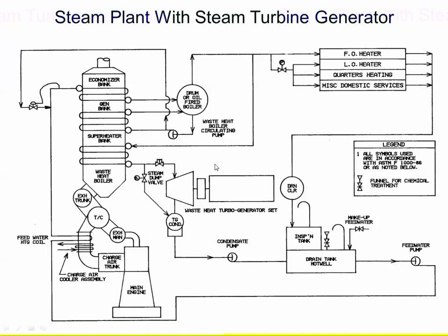And then here, my saturated steam is going to go through a superheater and into a steam turbine. The other thing I'm going to mention on this one is that it also has the steam dump here. But on this type of system, at sea, you control boiler drum pressure with load on the generator.